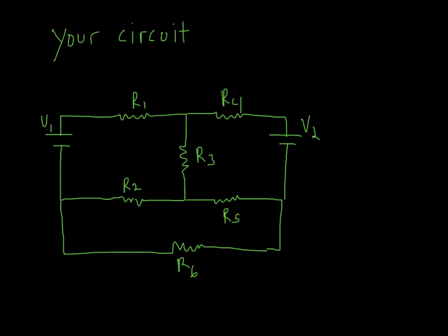And so what we want to do is we want to still simulate and calculate what we think we're going to have, but be prepared to be a little disappointed because you won't necessarily find all those components, and even if you do, their tolerance might be way off, so it's not going to match exactly. However, it's going to match close, and what we're interested in is the behavior, not the exact precise numbers. If we really are interested in the exact precise numbers, we'll measure our components and we'll go back and simulate it again and go back and forth.